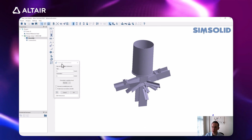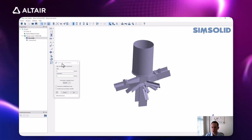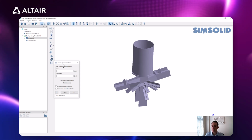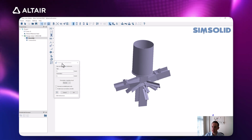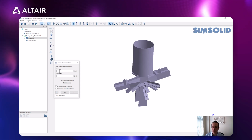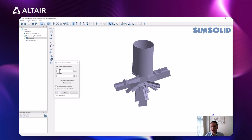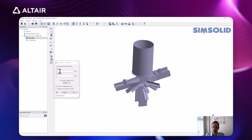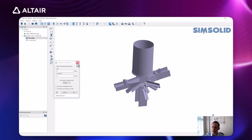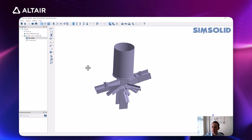And the first step is it's coming up with this automatic connections wizard, I guess you could call it, which I'm not going to actually go through right now. I'm going to bring this up later. We can use this to specify any tolerances or potential imperfections in our geometry that can be mitigated through the use of this gap and penetration tolerance. But I'm not going to do that right now. I'm going to click close, and I'm going to start by defining a couple welds between my elements.